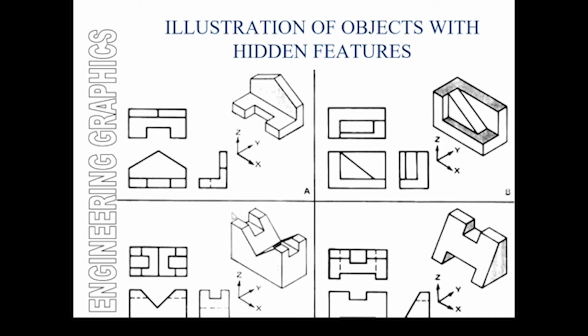So for example, an object like this, which is actually not something we see every day. However, once you look at it, you think, okay, that's quite possible. We can model that quite easily. When producing the technical drawing for that model here, you need to bear in mind that the details which are not apparent on the skin, so positive y direction, looking at the front view here, there is this cutout done, which can only be represented with that dashed line there marking the depth of that cut right there.